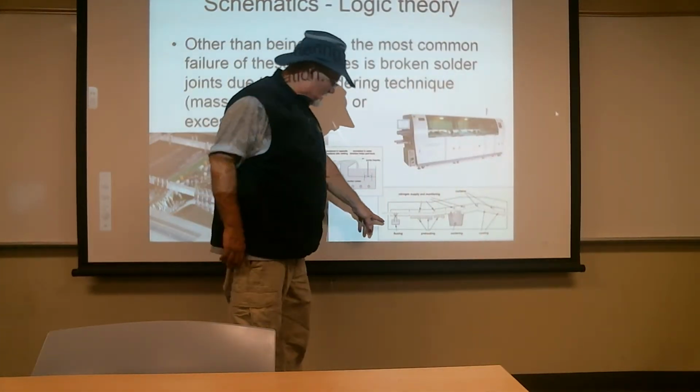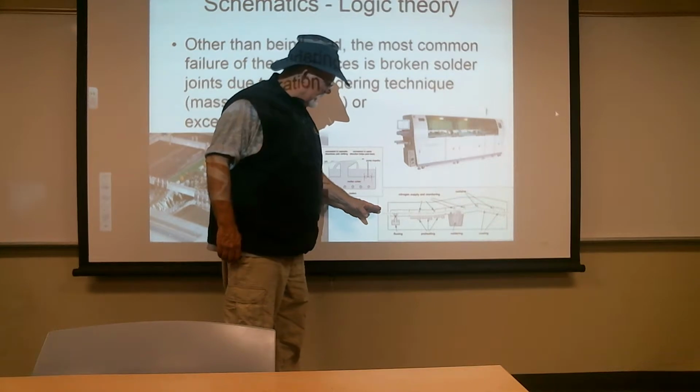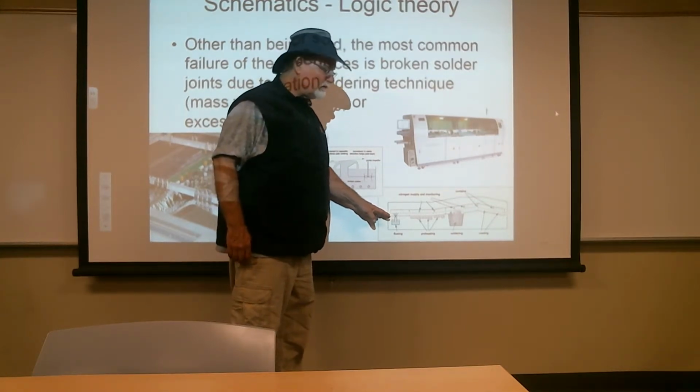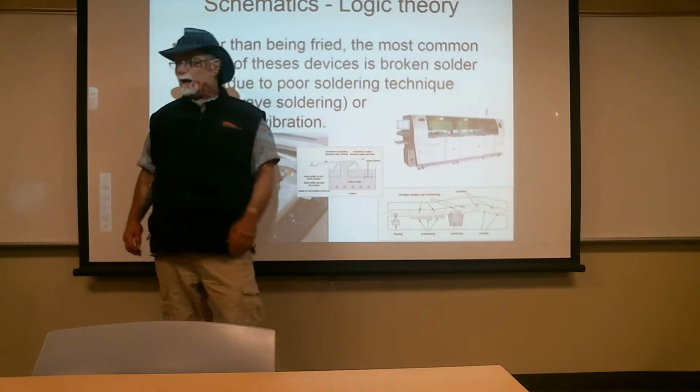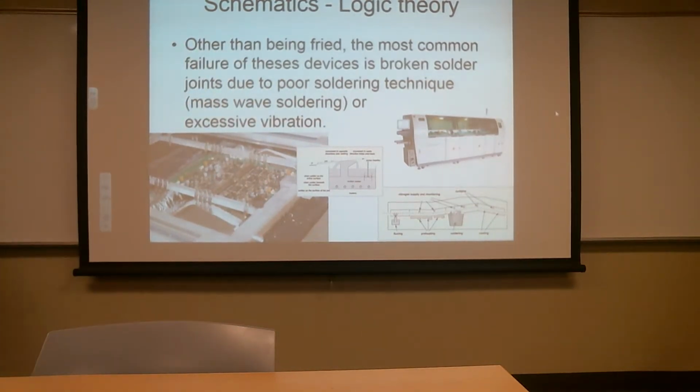So up here, usually again they pre-fluxed it. So fluxing may either remove anything that isn't pre-flux, or they can use a silkscreen template where the fluxing comes up and everything that is supposed to be fluxed has a certain type of silkscreen surface, and this fluxing flux sticks to it, and everything else it just washes right back off. So there's a variety of different techniques there. To me, though, it's kind of cool to see the silver wave of molten solder flowing.